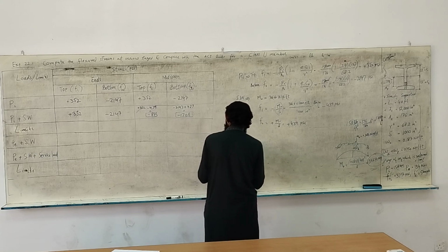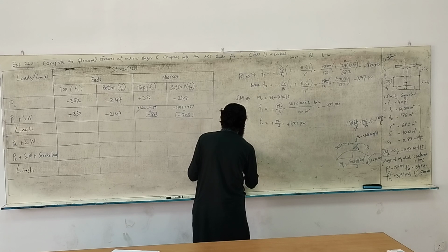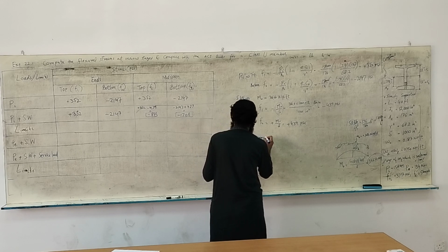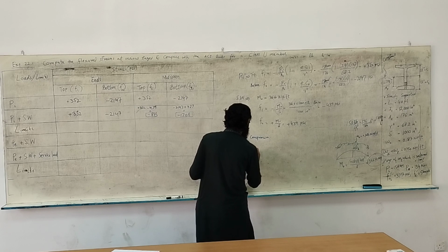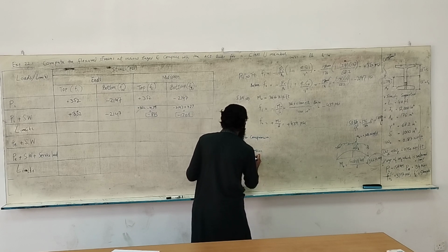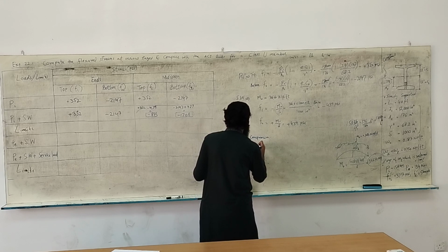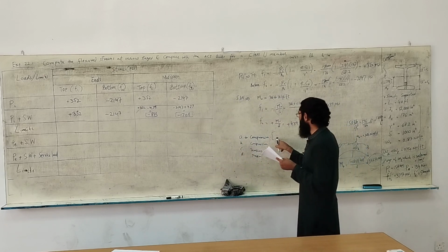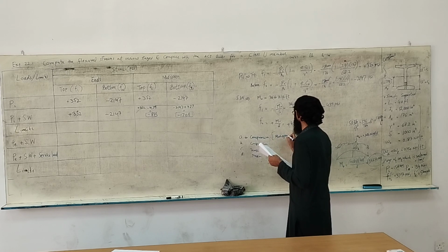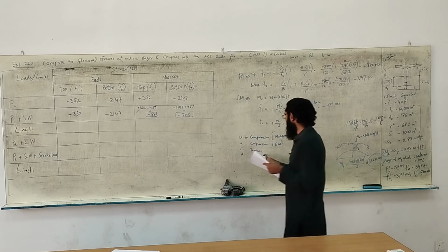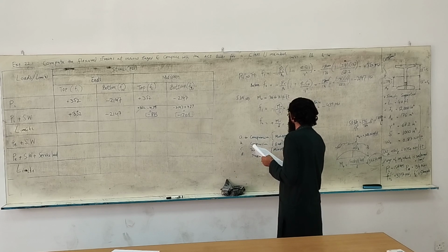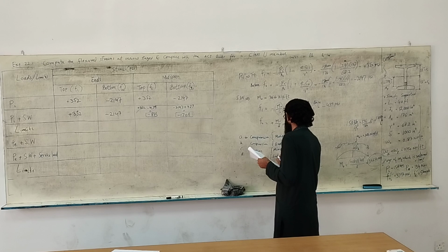So you should see that condition A, B, C, and D. Now, A and B are related to compression, and C and D are related to tension. Although it doesn't mention midspan, in this case we have the midspan. At the ends there is a separate clause for compression. For tension at midspan there is a different limit, and for tension at the ends we have different limits.